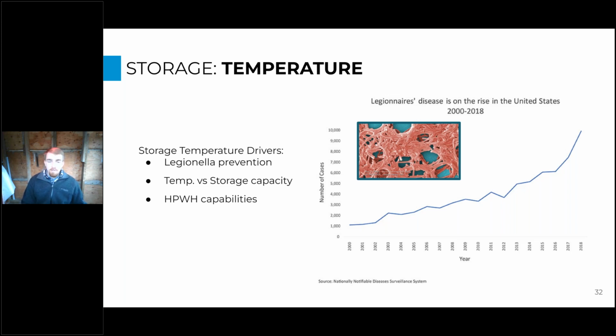So there's some manufacturers that'll have brochures that say, yeah, we can heat this water up to 180 degrees, but they can only do it if the air temperature is maybe 60 or 70 degrees or higher. So then in the middle of winter, instead of storing that 180 degree water that you're set to, now you're probably storing 140 degree water. So if your system's designed around 180, you might have some negative consequences there.